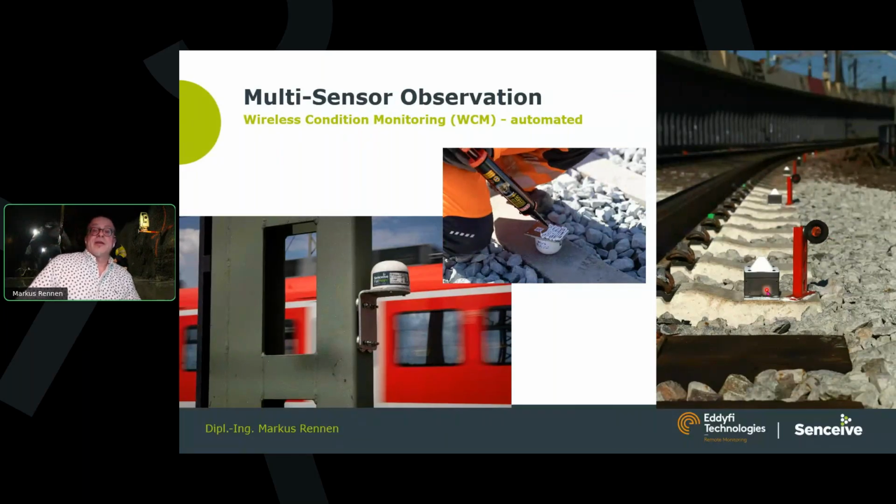Here, in this case, it was an interesting situation, as the total station was stolen twice. So actually, the initially secondary tilt sensor system was promoted to the primary system for observations, and the total station observations were only carried out occasionally afterwards. Installation, as I said, is very easy.